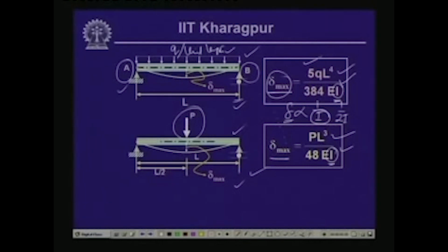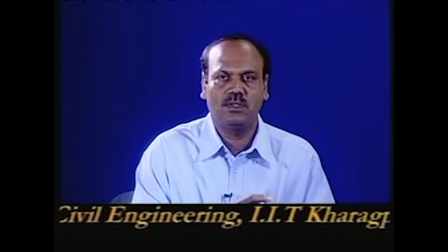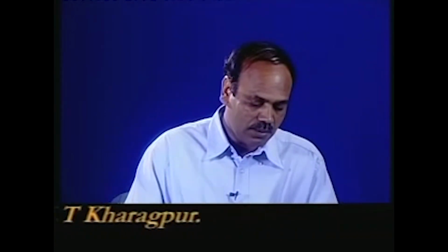So, this particular question which was posed is quite general in nature, wherein we have not talked about the loading on the beam, or the span or the length of the beam. What we said is that if the moment of inertia is double, what is the impact of that on the deflection. Now, as we can see from this expression of the deflection, whether it is a uniformly distributed load or a concentrated load, if the moment of inertia is double, the deflection is going to be half of the previous value, and this is the relationship between the deflection and the moment of inertia.